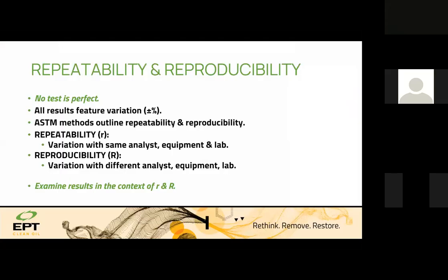which can cause problems. Final consideration is that when you are doing a test, remember about repeatability. Repeatability is the same lab, same equipment, same test. It has some errors. We need to know it. And if you are doing it with different labs, reproducibility is important. It means that the test being done by a different machine, different operator, a different lab, can have some errors. So be careful. You can ask your lab for a certain repeatability to be acceptable for a certain test. This can be done for critical machines.